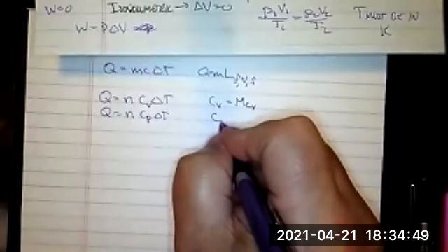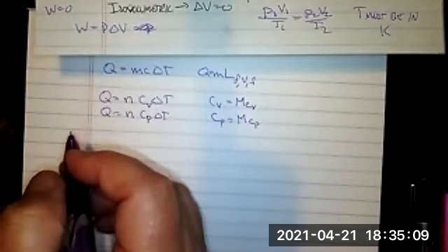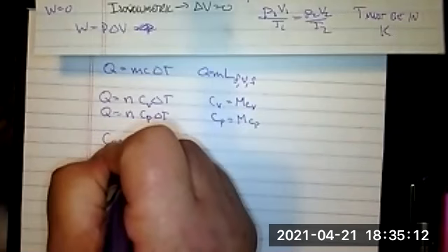Okay. And specifically, basically C_V is given by the molecular weight times the specific heat in lowercase units. So M times lowercase c_v, and C_P is equal to big M times lowercase c_p. Okay. So those are two typical things we use. And the reason why we use that is because it turns out when you start to study an adiabatic process, then you can work out, and your book does this derivation, it's kind of fun, but what you'll ultimately work out is that C_P minus C_V has a very specific value. C_P minus C_V is actually equal to R.